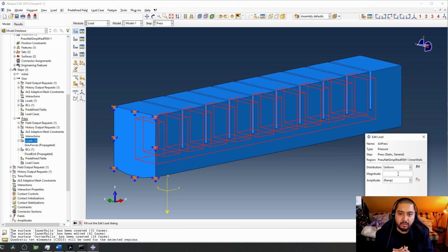If you have a little bit of experience with these soft pneumatic actuators, they work maybe from 0.1 bar to maybe 1 bar in the range. Bar is used just because the manometers usually are in those units.